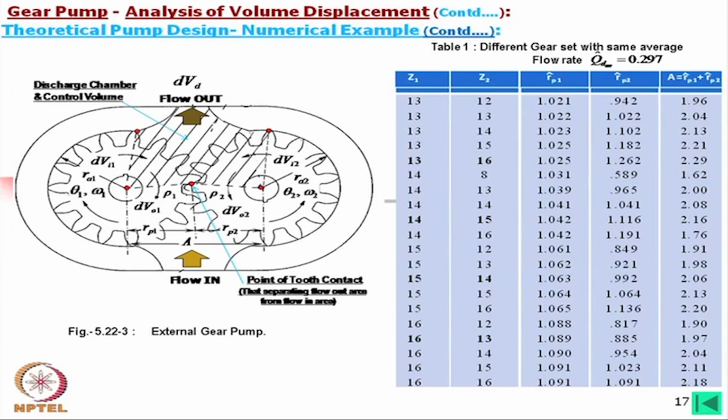severely undercut. Okay. So, therefore, in this case, because this is dimensional analysis, we can simply say that this is the module used for the flow. We will not consider the correction of gear teeth, because with the correction of gear teeth, this volume will definitely vary while we analyze the contact point. We must introduce that correction part in that analysis. But in this case we shall not consider it, or this calculation is made without considering that these are corrected gears; these are uncorrected gears.